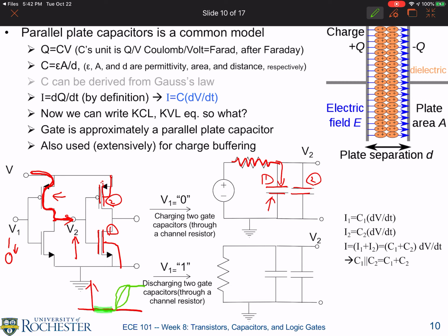We'll develop an intuition in just a moment, but it's charging. It doesn't go instantaneous. Why? Because if it goes instantaneously from 0 to 1 volt, then dt is 0, and dV/dt is infinite, and that means we need infinite current, which is unrealistic in non-ideal circuits.